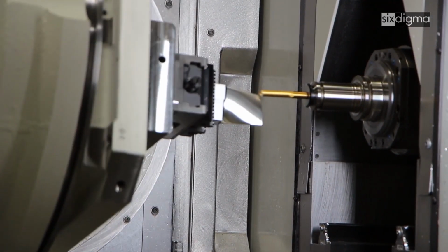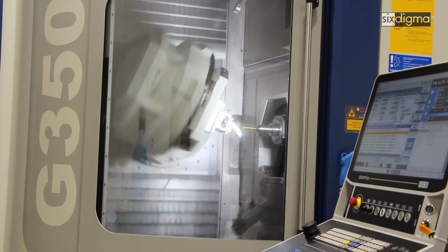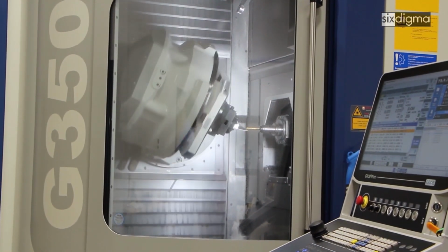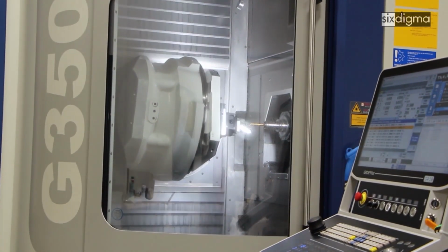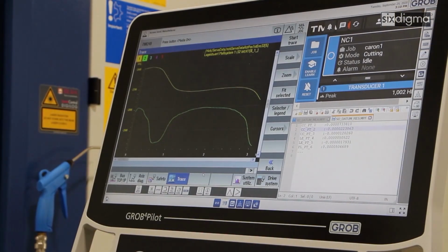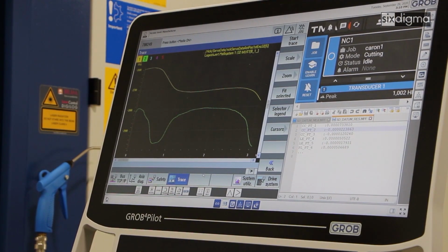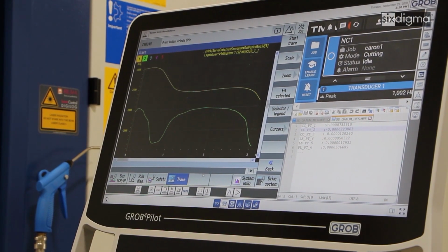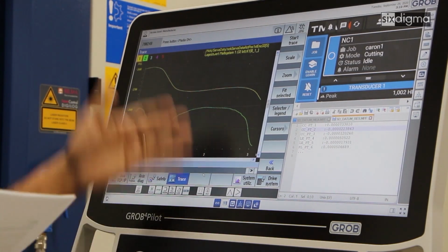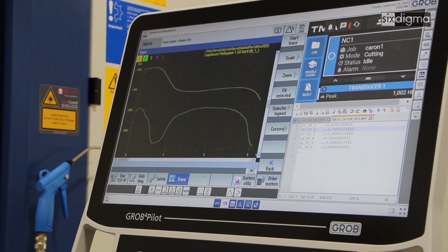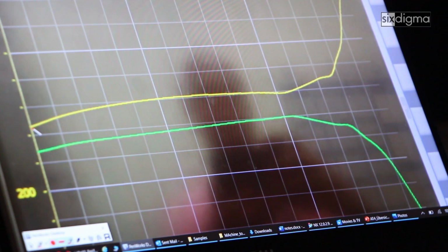There are instances, however, where these axis reversals are so hard to predict and identify. To circumvent this problem, Siemens provides an onboard trace diagnostics for each axis, and we can monitor a variety of machine parameters using this trace function. In this example of the tool axis trace, the top curve shows the main rotary axis of the table.